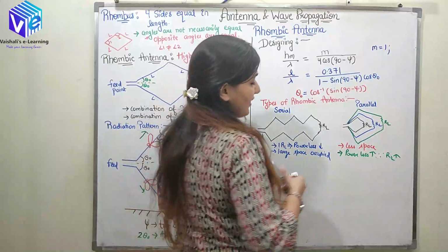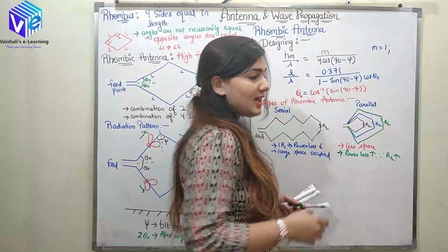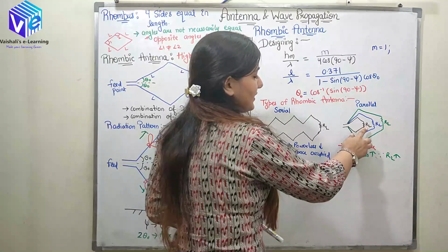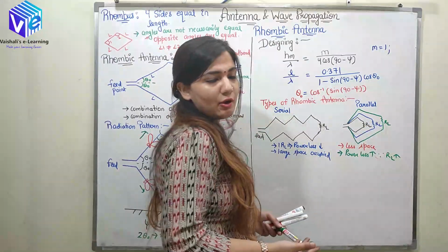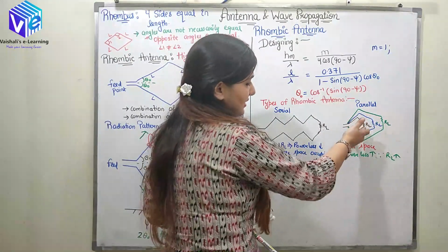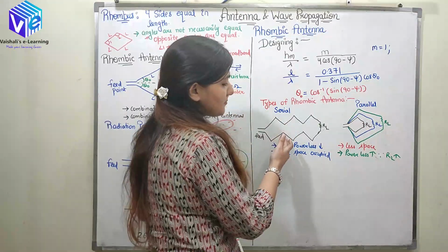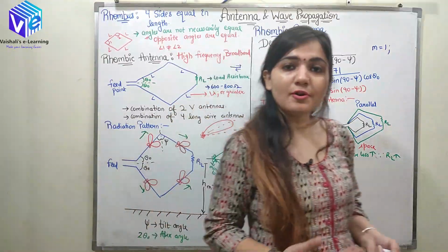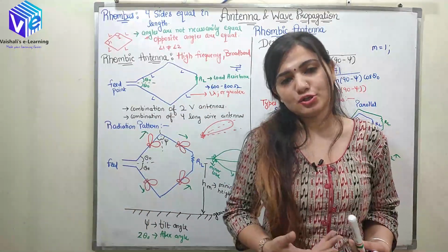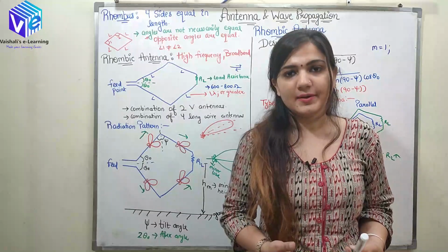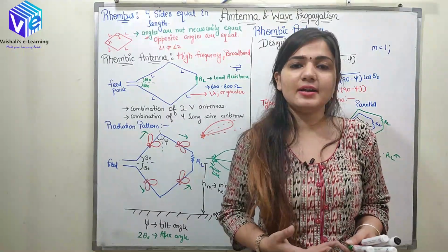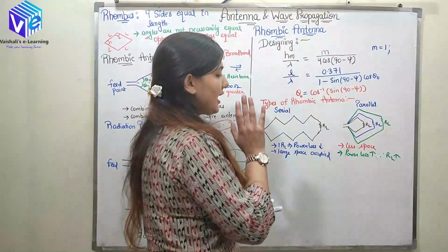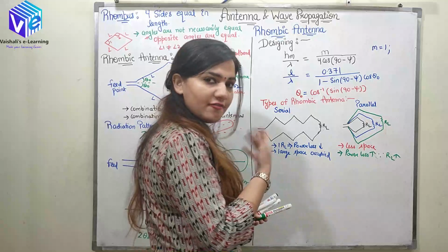Whenever I have more load resistance at the load, I know the power is dissipating. The power dissipating is resulting in the energy loss. So efficiency is less in this case, but efficiency is more in the serial case. But it is taking more space, and I hope you know that space is a serious issue whenever I design an antenna. I need the antenna to be as compact as it can. So I hope now you know the advantages and disadvantages of both of them.